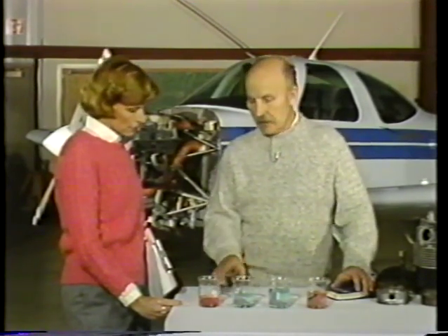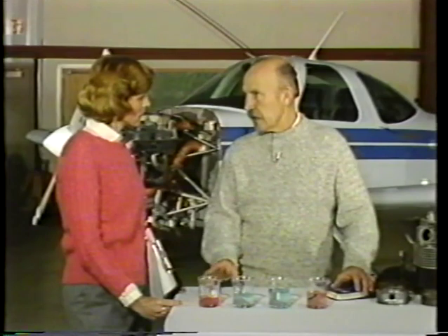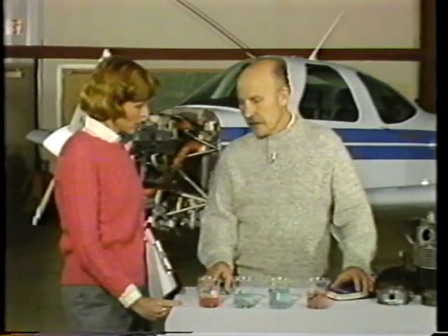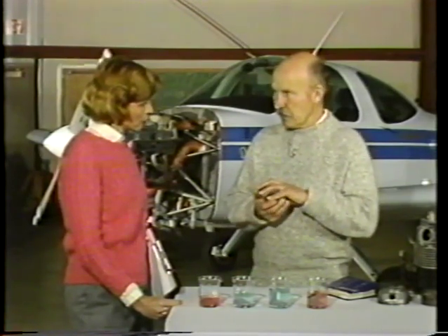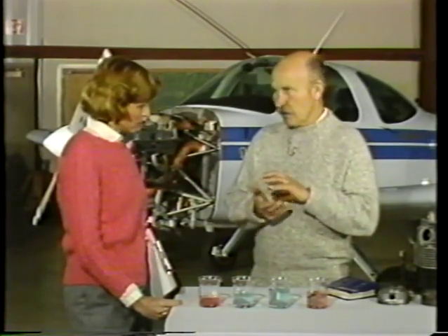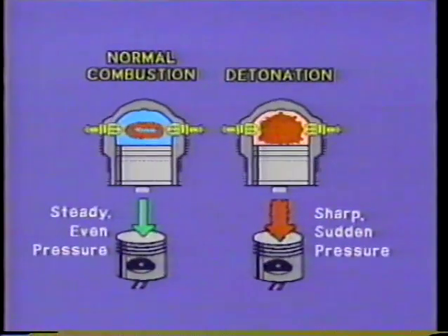If we do mix the wrong grades of fuel in there, then detonation can occur. Now, detonation is a characteristic, as I said, of the fuel as it performs in the combustion chamber. Normally what happens in the combustion chamber is that the fuel-air mixture is ignited and it burns slowly across the fuel-air mixture. This provides an even pressure on the piston to push the piston down and give us a good uniform pressure in there. Detonation occurs when normal burning starts and then the fuel-air mixture explodes, and this gives us a very sudden shock to the engine.